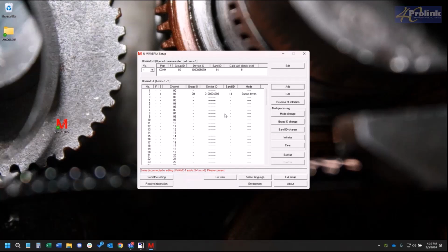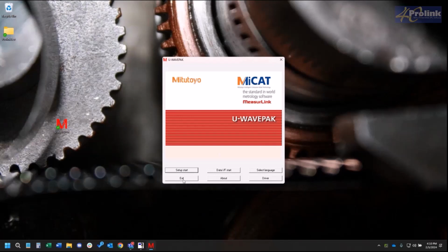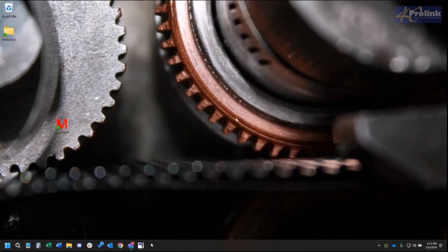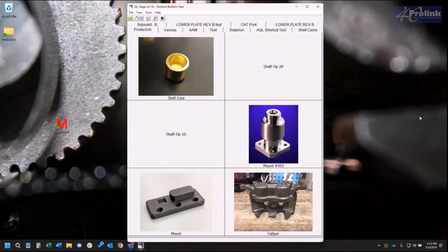The completion of pairing takes place when you push the data send button on the gauge one time and then a second time. Once you push it the second time, you will see blue text at the bottom line, and this will indicate that it's successfully received a number from the gauge. You can test this if you choose to by pressing the send button again and noting that the value shown in the window will be the exact value that is on the gauge. This now completes the pairing of the gauge with the receiver. You'll now exit this screen and exit the main screen.